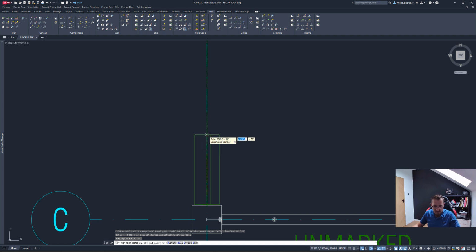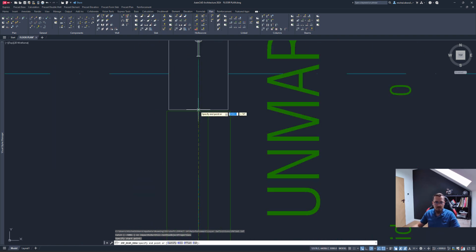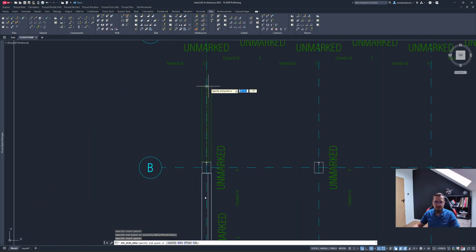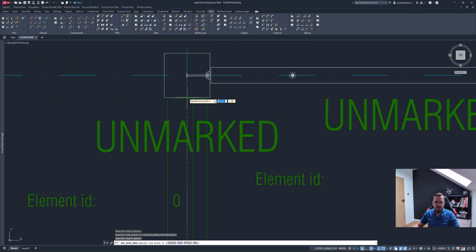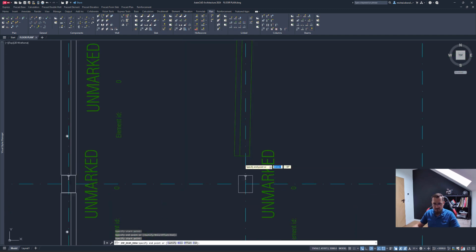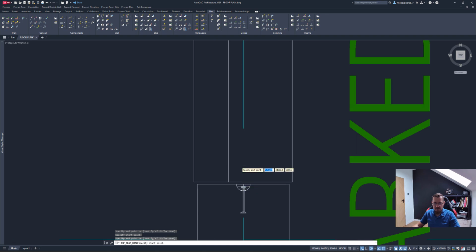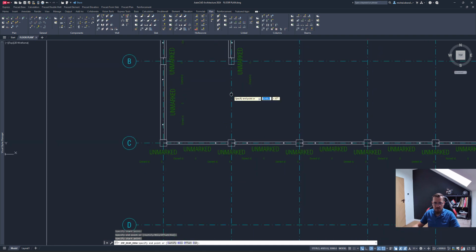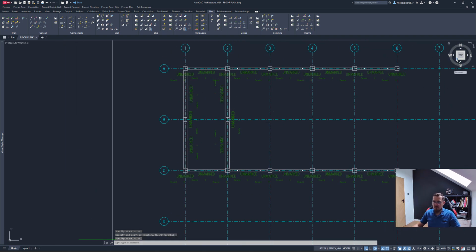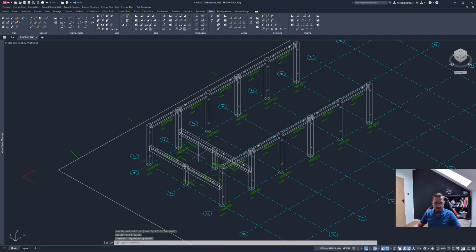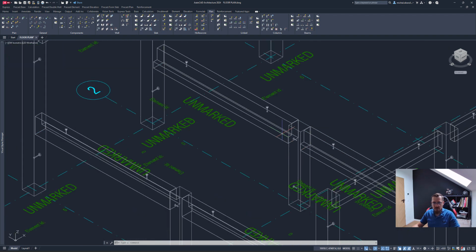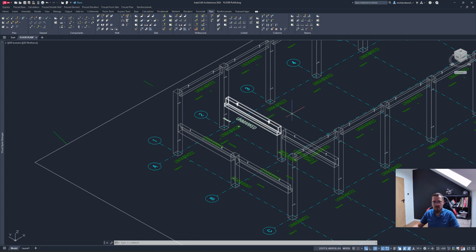And offset is applied. I can see that, which is good. Yep, that's good. Same thing here. Let's apply that. Yep, that's clicked. Now I will go the other way around, so from top to bottom for the left side. Yep, and like so. Okay. If we rotate the model, now we have ledge beams, as you can see, solid geometry here. And yeah, that's how we can place those elements.